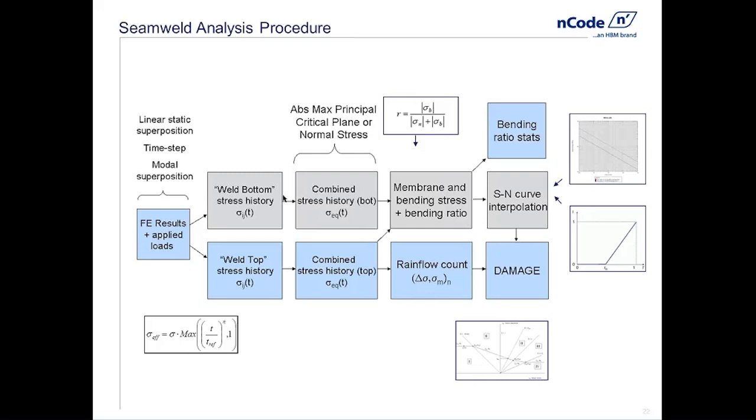And all we've actually done in this particular implementation is we've basically replaced the stresses that come in. Instead of being shell stresses recovered top and bottom, they're the linearized stresses that we go off and calculate an effective top and effective bottom stress. So the rest of the methodology in the fatigue calculation is the same as with the solids.